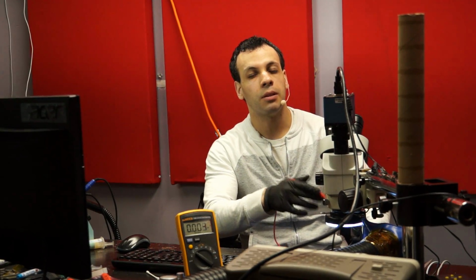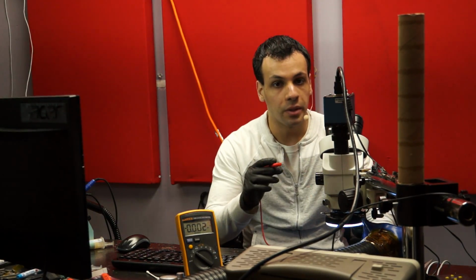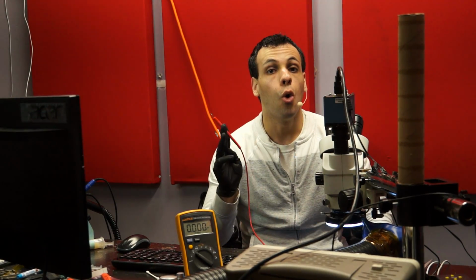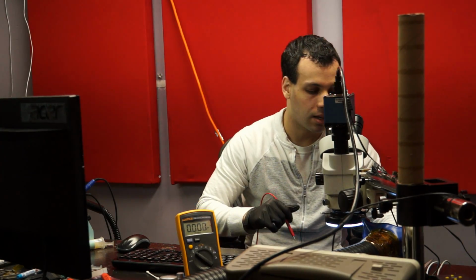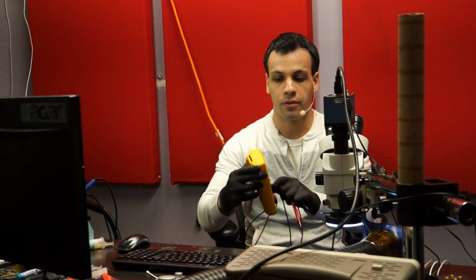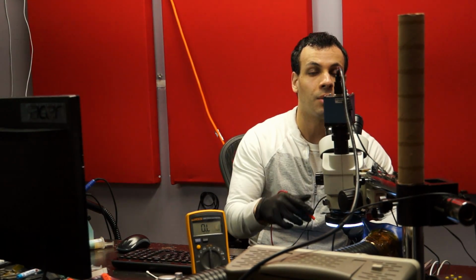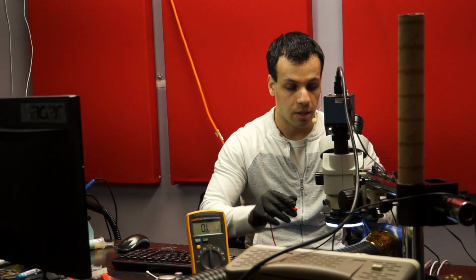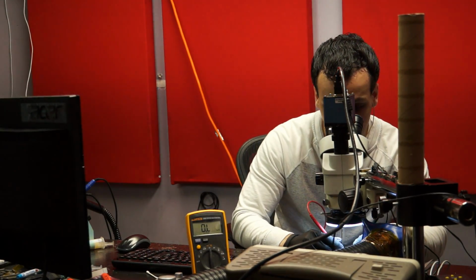Okay, so now we have 2 different things that could be wrong here. Either that resistor is blown and not allowing SMC PM G2EN to the U7200 buck converter controller, or the buck converter controller is pulling the signal down on the other side of that resistor. So if that resistor itself is higher than the 100 kiloohms that it's specified for in the schematic, that means the resistor is blown. However, if that resistor is 100 kiloohms or lower, that means the buck converter controller chip is what's pulling the SMC PM G2EN signal down.